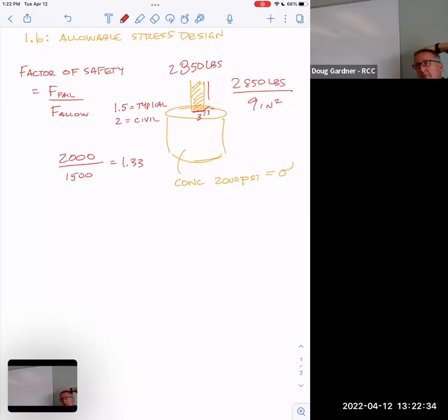I mentioned one time, for instance, that if you have a footing down here and a wall on top of it, and the dirt's going to push the wall over, does it make sense? The back of the wall right here is going to lift up. And so the vertical rebar in the wall, they want it toward the back, not just in the wall. The guys out there tying wire and stuff are like, who gives a darn, and they just tie wire and don't pay any attention.